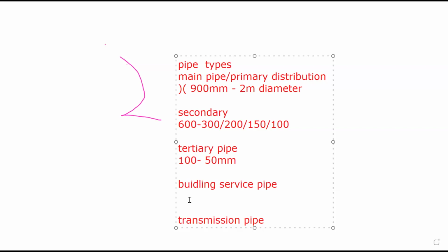The other way to estimate the volume and sustainability is through river gauging. If you are using surface water from a river, you know that during the rainy season there's a lot of water in the river, and in the dry season there's little or no water. The volume you are going to use is the volume for the dry season. Remember, you don't take 100%. You take maybe 50, 60 or 70%, because you must leave some to continue downstream to preserve biodiversity.